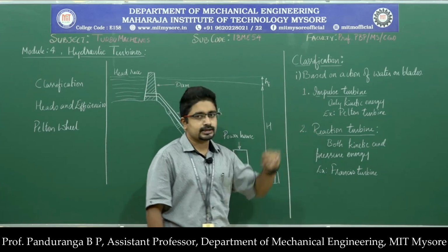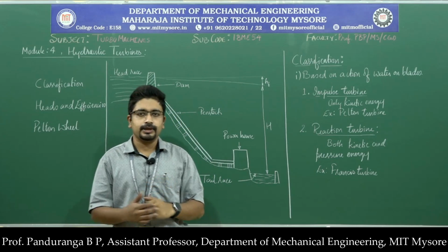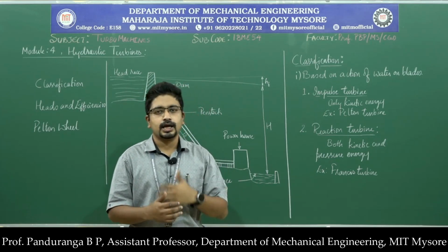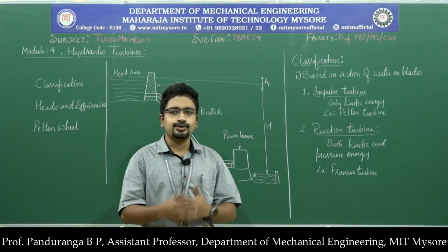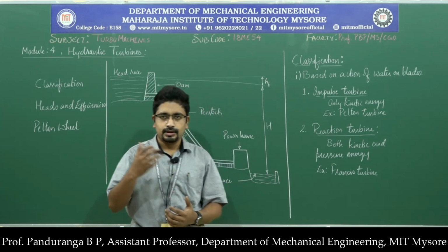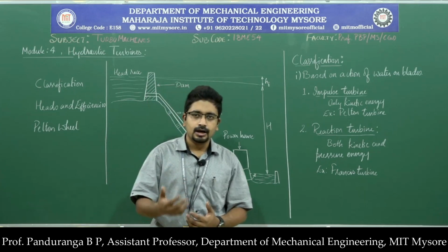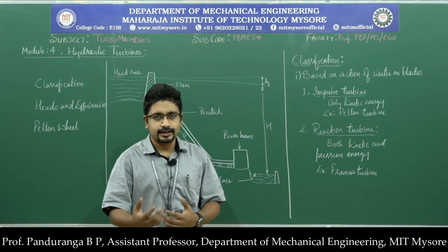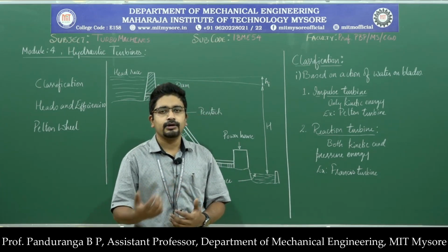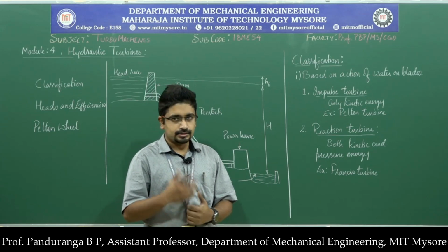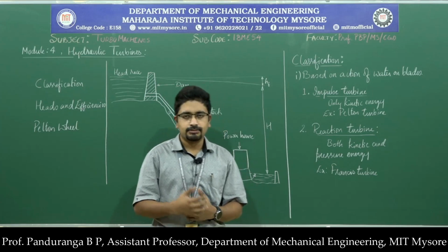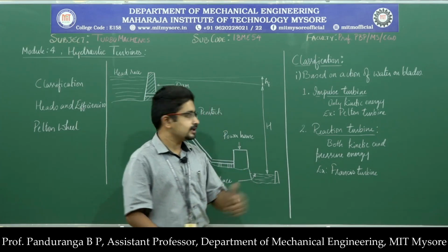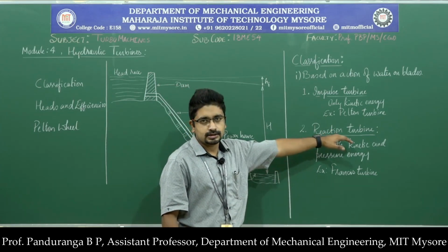Then we have the reaction turbine. So, in the case of reaction turbine, there will be changes in the kinetic energy as well as pressure energy as the water flows through the turbine. So, the blade or the runner absorbs a part of kinetic energy and a part of pressure energy. Because of the change in pressure energy, there will be a reaction force, and hence the name is given as reaction turbine.